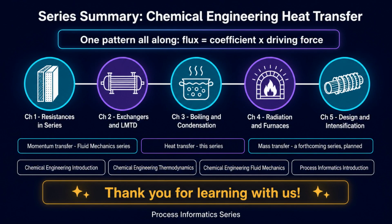Five chapters, one sentence each. Chapter 1 built the overall coefficient from resistances in series and showed which one dominates. Chapter 2 turned that coefficient into hardware through Q equals U times the log mean temperature difference, and the exchanger configurations that make that mean temperature meaningful. Chapter 3 added phase change, the enormous coefficients of boiling and condensation, and the burnout and hazards that come with them. Chapter 4 introduced radiation and its fourth power law, which is why furnaces at high temperature are a different discipline from exchangers. Chapter 5 assembled all of it into networks, fought fouling, and shrank the equipment.